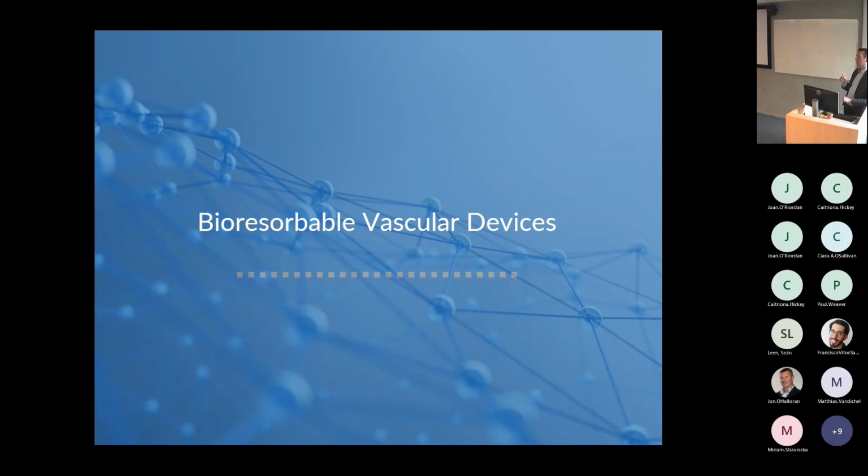They tend to corrode very quickly, and they have to be protected heavily by coatings. So for a small structure, a small amount of corrosion, it's going to be gone. So it is very size dependent. But for large structures, as you go beyond implant size, pitting corrosion probably isn't that bad until it gets really severe. So yes, there is a definite size effect in what we're looking at.